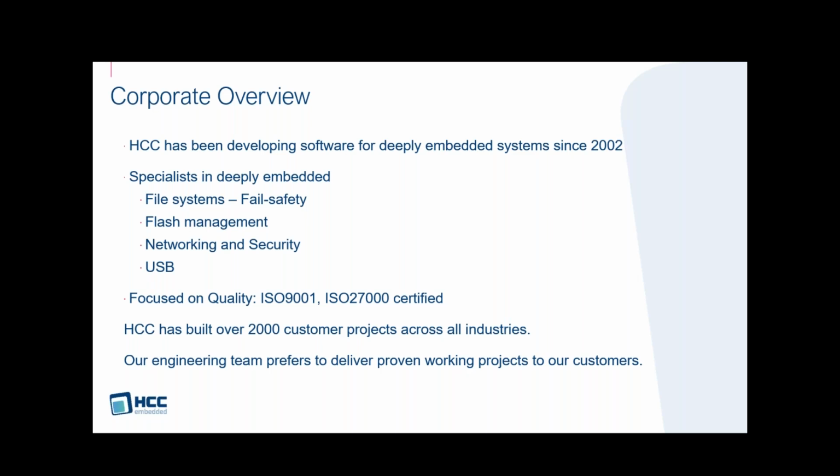Back when we started, the largest NAND flash on the market was about a 32 megabyte chip with a 1-bit ECC requirement. That means you need to correct 1 bit per every 512 bytes to make that device stable. Now we've got to a point where the biggest chips are about 128 gigabyte with maybe 40 bits of ECC for 512 bytes of data.